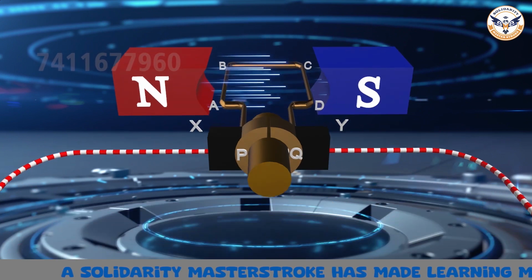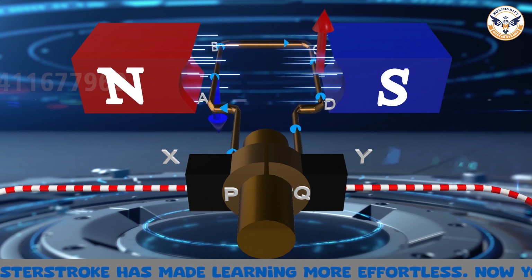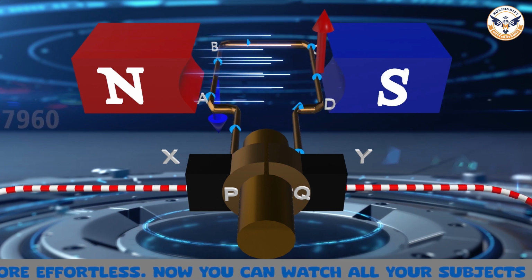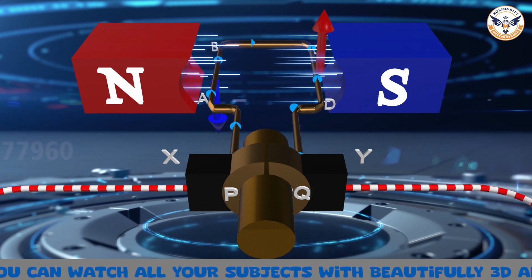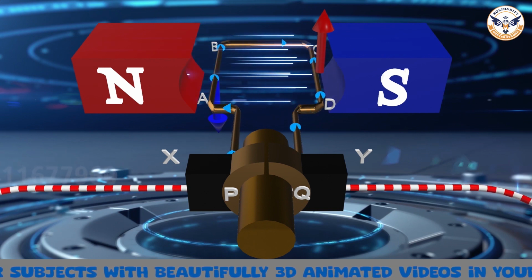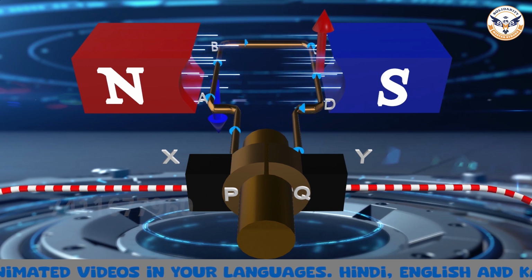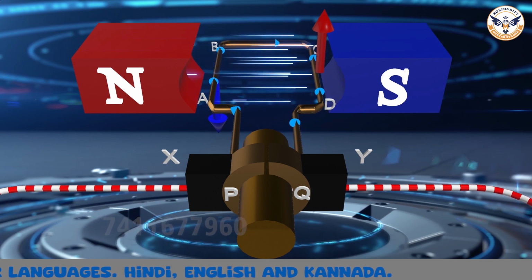Now, let's understand how it works when the switch is on. The current enters into the coil ABCD from the source battery through conducting brush X and flows back to the battery through brush Y. Notice that the direction of current flows from A to B in the arm AB and C to D in the arm CD. That is, in the opposite direction to current flow in AB.